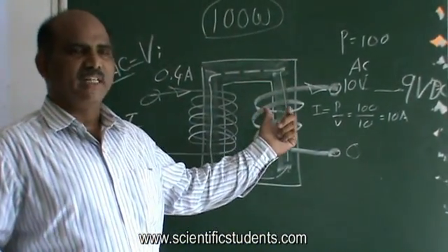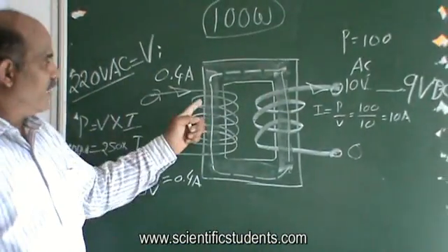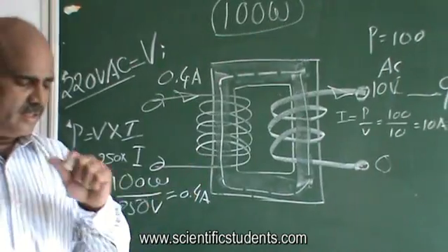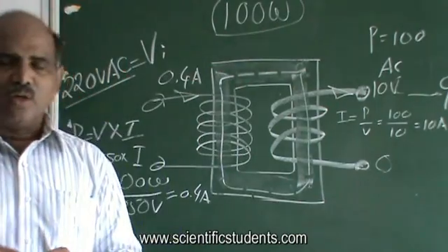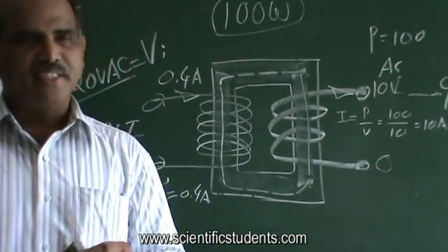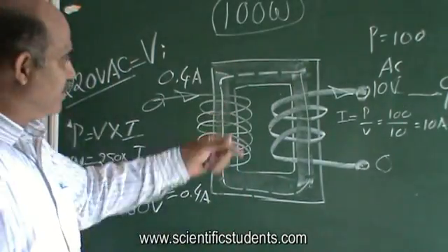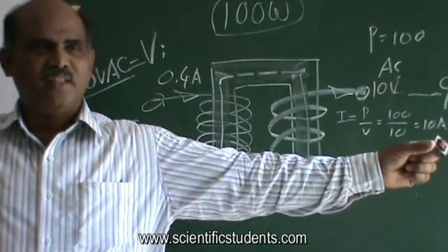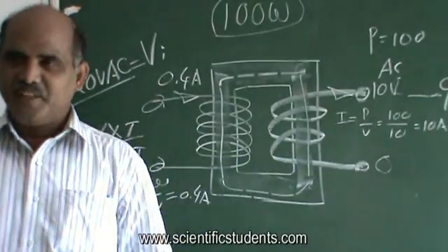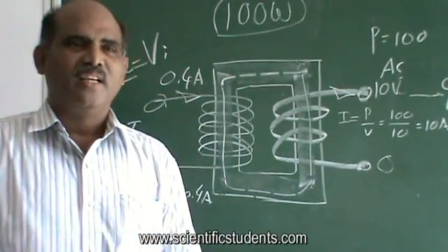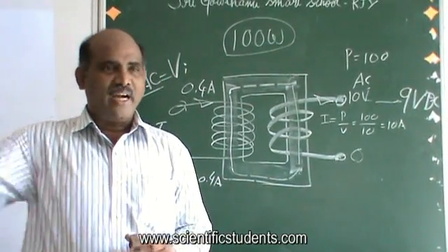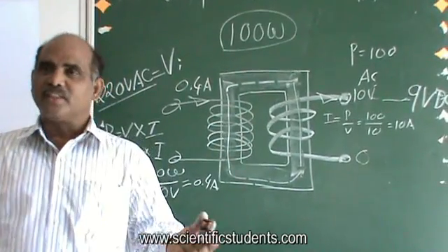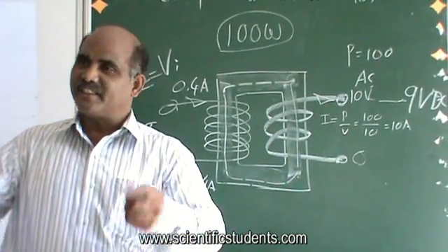for you it is just a 2 minute job, because there are more number of turns here. It is thinner, but more number of turns. When it is thinner, the resistance is high, and more number of turns means the length is more, and as per our first day's class, resistance is directly proportional to length. Because it is thinner, resistance is more, and because of the length, the resistance is more.